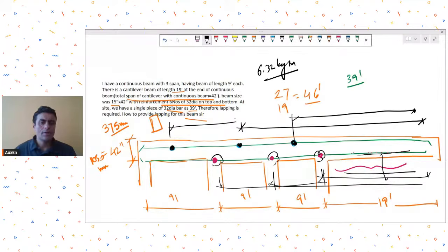All right. So Mr. Tamilarasan is asking, can we have lapping for the backspan of a cantilever? Now try not having, see, and now try for this bar. Now people say that, let's say in the first half, you will get the maximum cantilever moment, and then it will come to zero, let's say. So try not having a splice, maybe in the backspan portion.